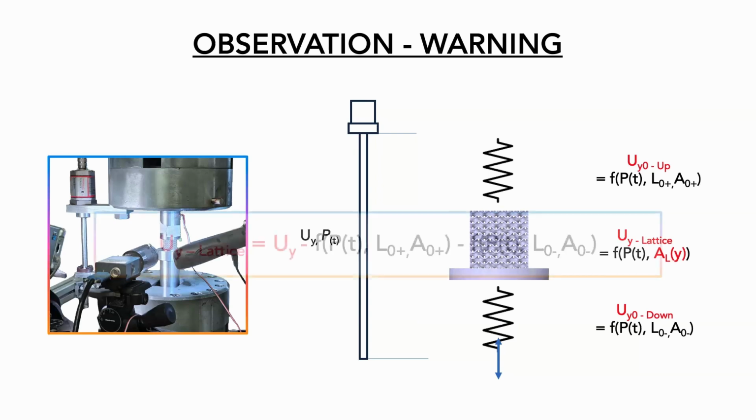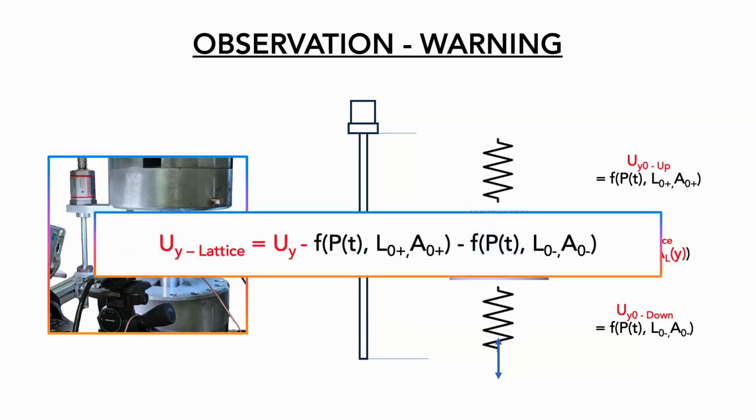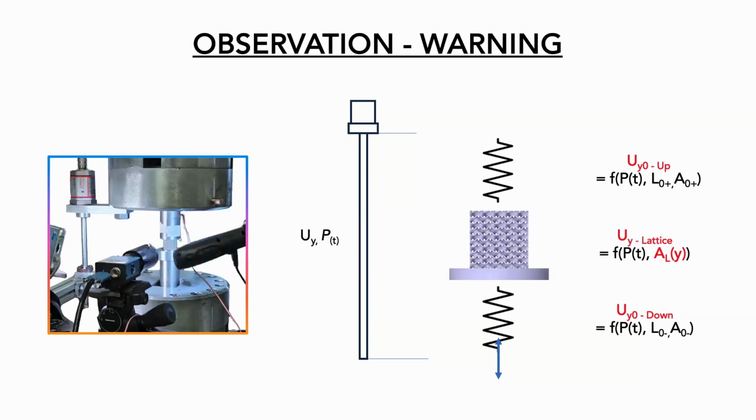So we applied a very easy correction, so our results are more accurate to the DIC measurements. It's worth noticing in the previous slide that we cannot apply it directly to the lattice because we don't know the distribution of the area. So the stress and how the load is managed by the lattice is a very big problem, as you know.